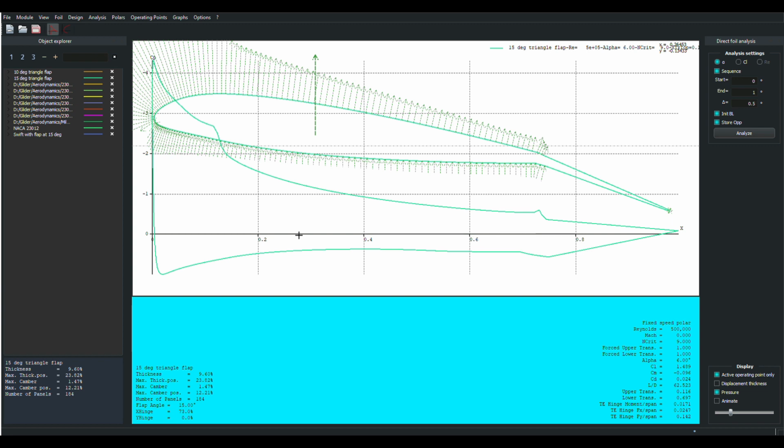So what we see here is that at 6 degrees, we're beginning to see some of the barrier develop here. It's a little one, it's not big. This is 15 degrees of deflection. Once you go to 20 degrees deflection on this, that barrier is back to fairly significant, and these pressure spikes here are much taller.